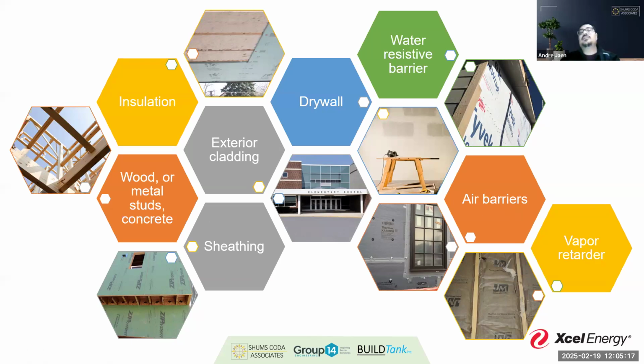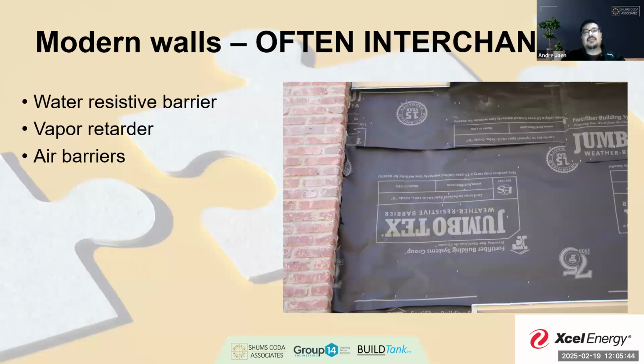And there's some really good articles and things that I can point you to when it comes to discussing wall assemblies or roof assemblies with double vapor barriers and things like that, where it's like, hey, that goes against conventional knowledge. That's not supposed to work that way. Or we're creating a dew point there and things like that. And so we've got to think about the times in which some of these products can do more than one thing. Are they acting in a similar way? And what's that permeability and where's that happening? So that's really going to be the basis of our discussion today.